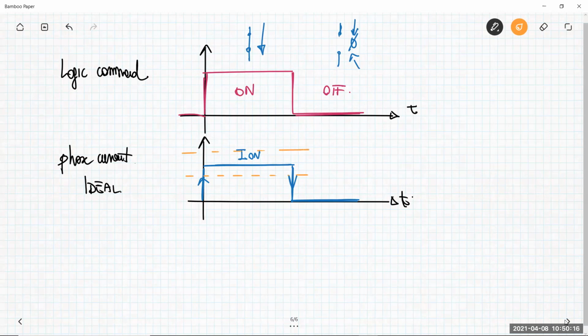Not lower than a minimum value, because I want to obtain a specific level of current to generate the magnetic field needed to make rotation possible, so to generate the torque I need. Currents that are very low cannot excite enough magnetic field from the stator to make the rotor move, and no more than a maximum value before you can have some overheating problem.